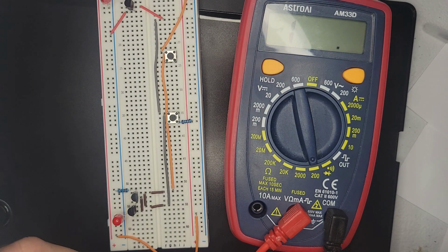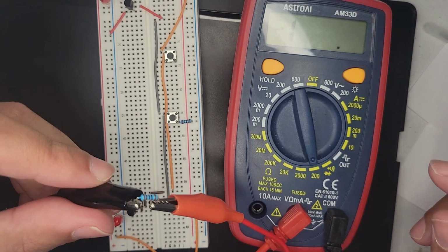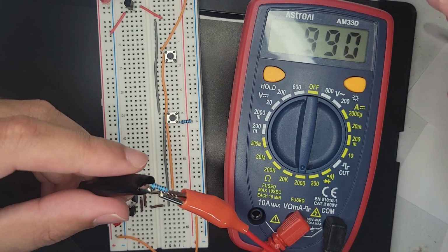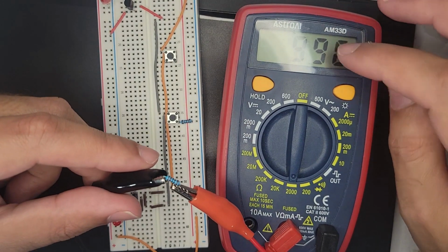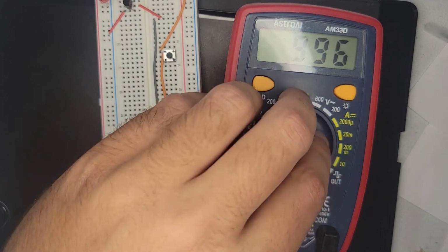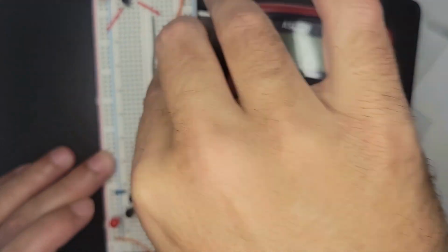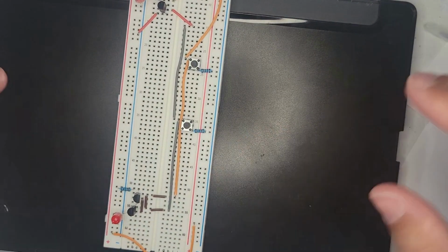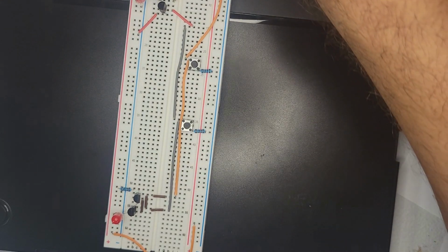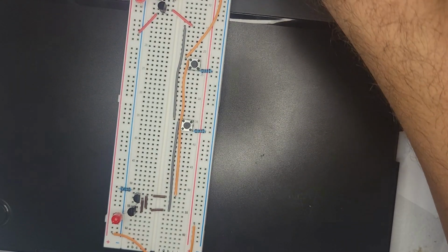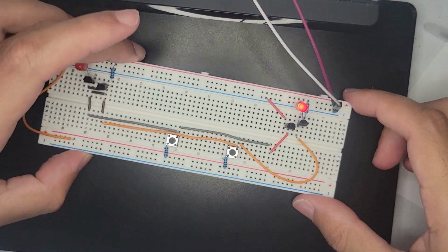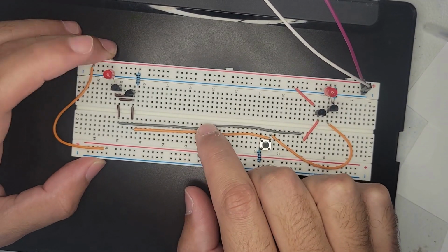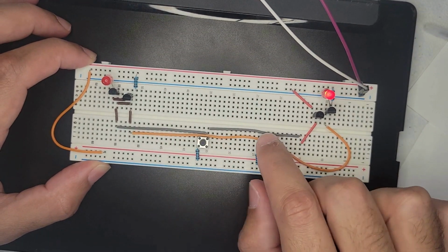So I have this other resistor that I had seen there. Maybe this is the one that I cut. Yeah. Okay. So this is 1,000 ohm. All right. So let's at least fix that problem. So I'll turn this off. I don't think this will really change anything, but if anything, it should have helped me with all that current. I'm going to plug in my power again and just see what happens. Just make sure. So our not AND gate's light is on by default, as it should be. Press a button. So he's still behaving weird. So we know that this guy is receiving a positive voltage, the OR gate. So I'm going to skip worrying about that for now.